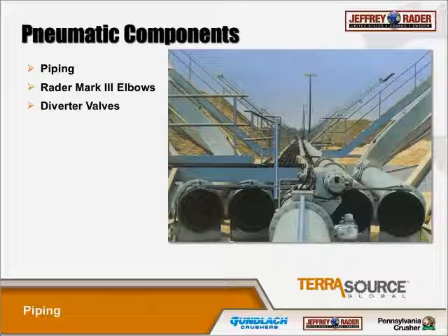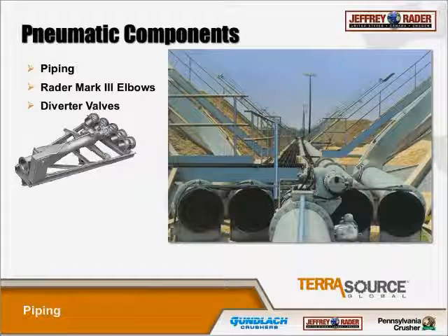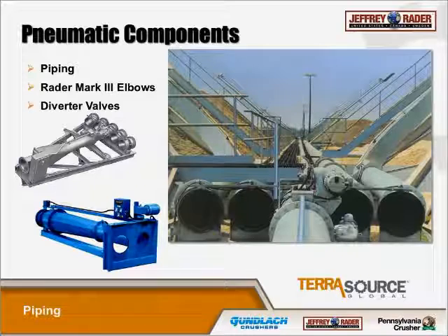We also have diverter valves, which allow you to redirect the pipe to multiple locations. We've got 2 different types of valves here. It's the 09 valve, which moves in 10-degree increments, and G valves, which move in 7.5-degree increments. They're similar, but have their differences and have their advantages in different scenarios. We offer these valves in both a manual positioning system or an automatic positioning system, which uses gear motor drives and limit switches to change that pipe.